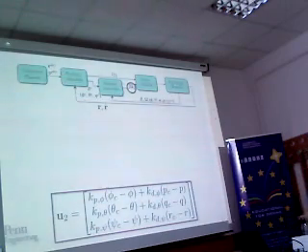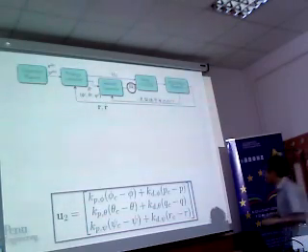And in this situation, you have to choose the KP and KD precisely in order to get a fast response. If you do not choose them right, maybe the system will not be stable.